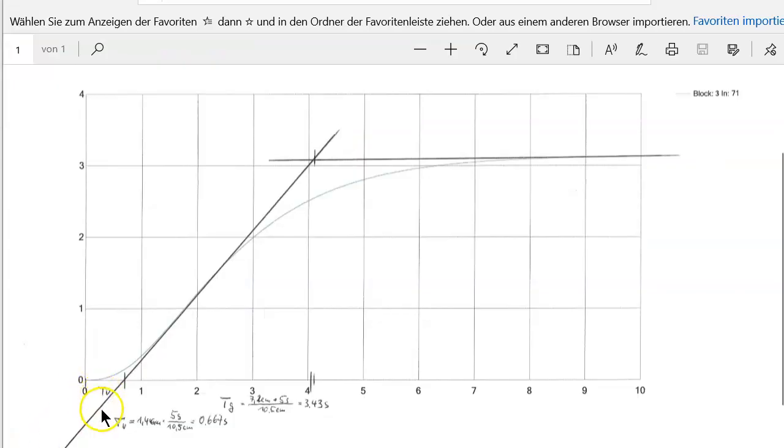So look what I have done. You see here the curve. This is my step response. I draw the final value, a straight line. I draw the inflection tangent. Then I get this cross point, the time between 0 and this cross point I measured was 1.4 centimeters.